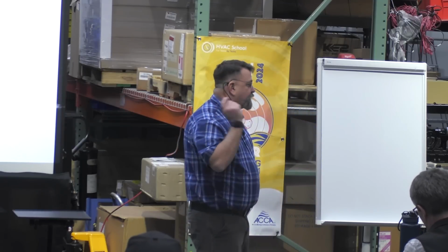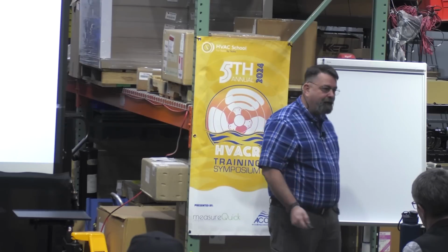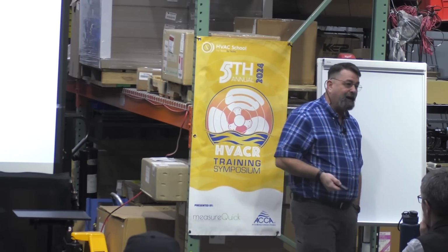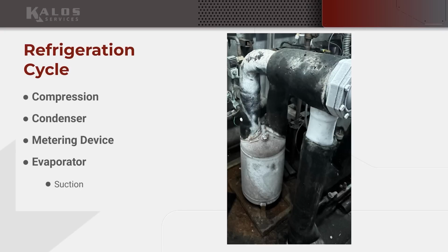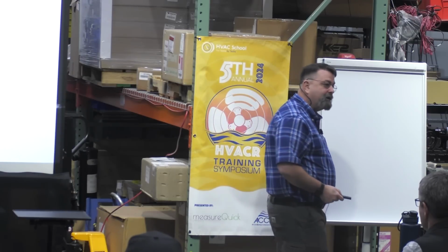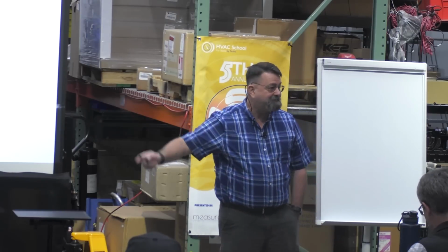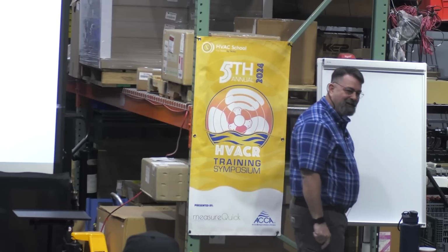Why? Well, I just told you I'm running ice cream at minus 25 degrees. If I'm superheating that refrigerant, that means I'm bringing this refrigerant back, could be as low as minus 10, right? This rack house might be sitting outside in South Florida in July with humidity. You think maybe I'm going to sweat? Yeah, I'm going to sweat. Is it going to be water? Not at minus 10. It's going to be snow, right?